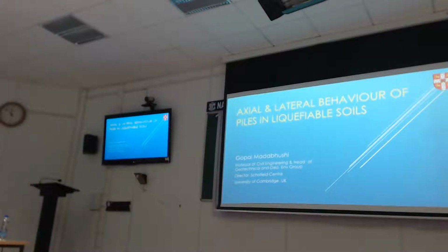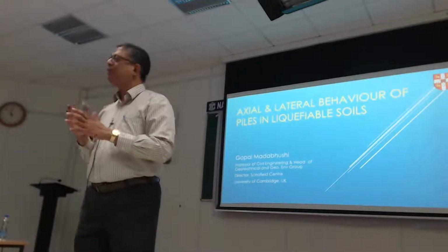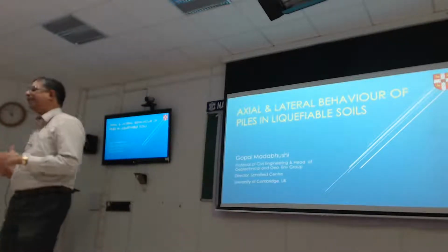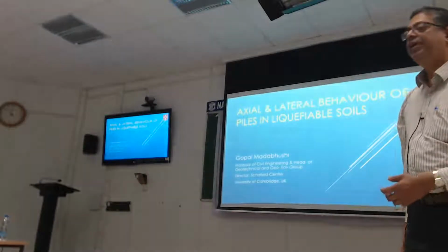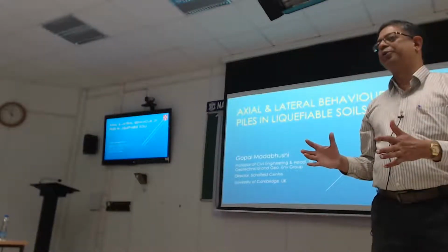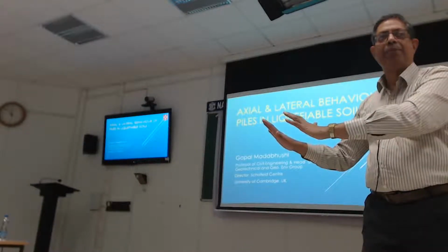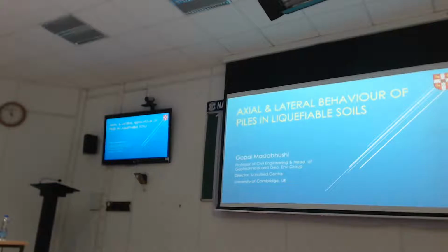So now we want to translate slightly from looking at the axial behavior to also the lateral behavior, because of mostly the lateral spreading problem. I've given you examples of that before, and I'll probably show some more later on. But if I have a pile group which is carrying all the load, the last thing it wants is some big lateral load being applied at the same time. And that makes the problem much worse, both from a buckling point of view, but also from the whole stability point of view.